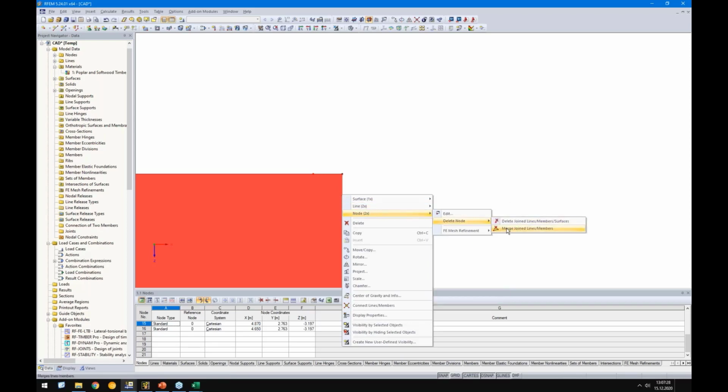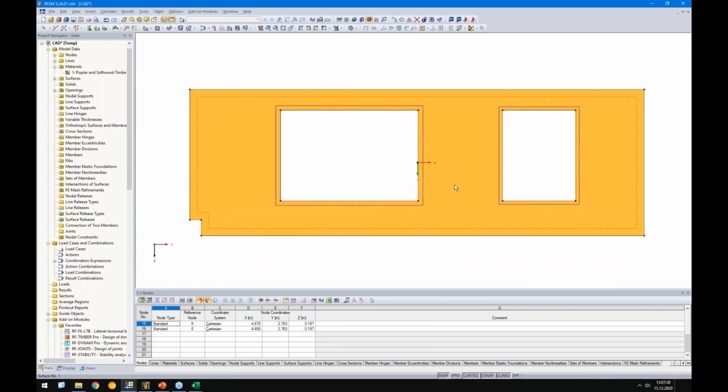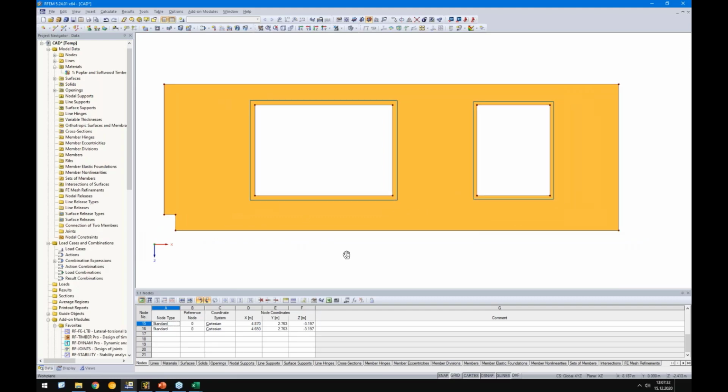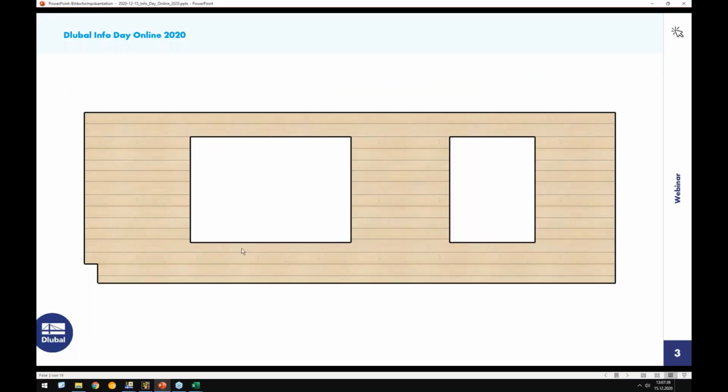Right side, I mean. All right, so now we can start actually by adding the loads, supports, and so on. But before we do this, let's think about what needs to be checked and what is important. You see here the rendering of this surface, and it's clear when there should be a support on the right side that the outer layers should be orientated in horizontal direction.